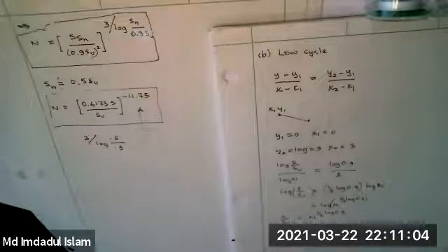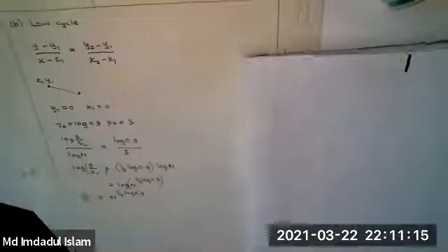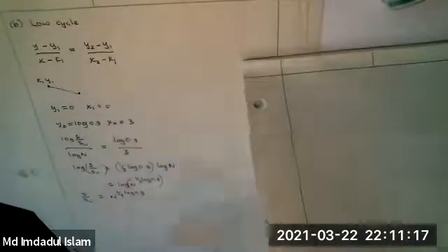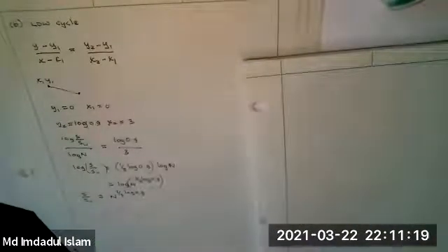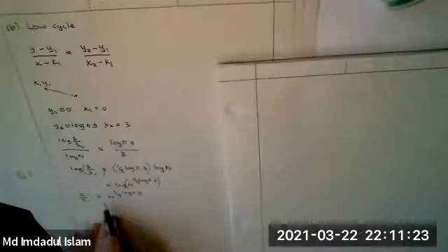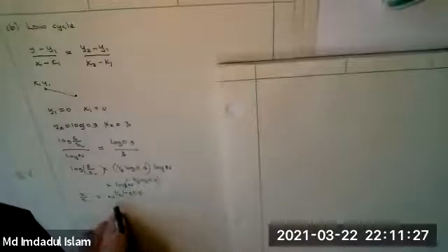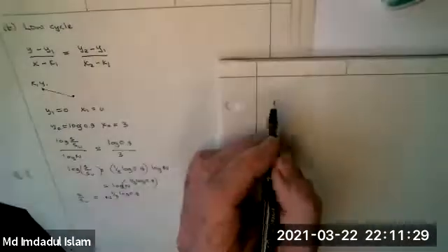It's more customary to go and get N in terms of S. You could actually use this formula for a given cycle life; this will tell you what S is. It's common to use these things to estimate life for a given S. In which case, whatever this power is here, I take the reciprocal of it, which gets rid of it here, and put it over here.